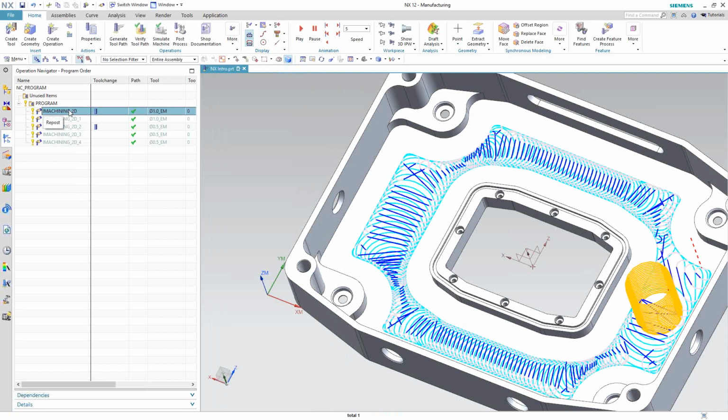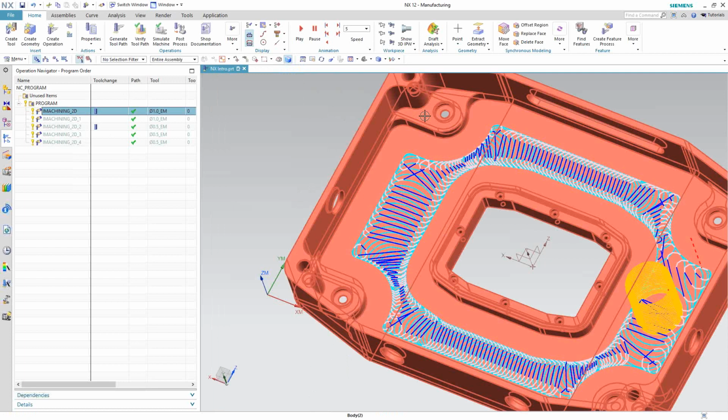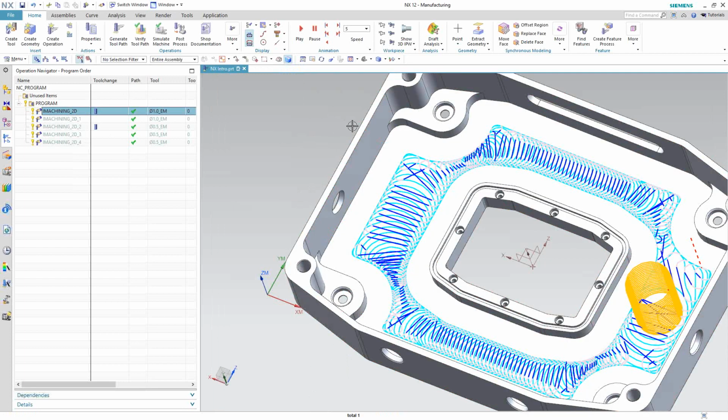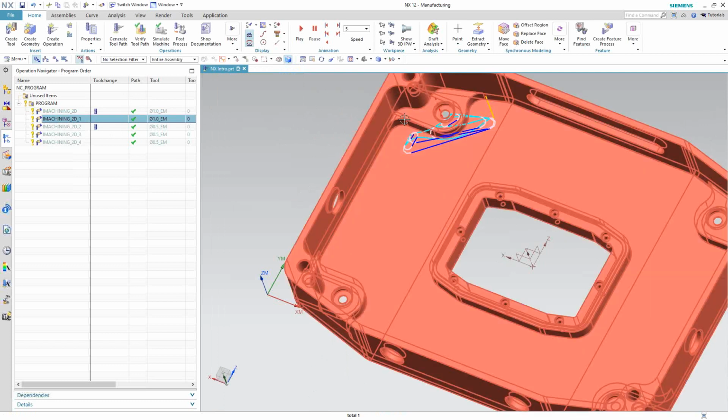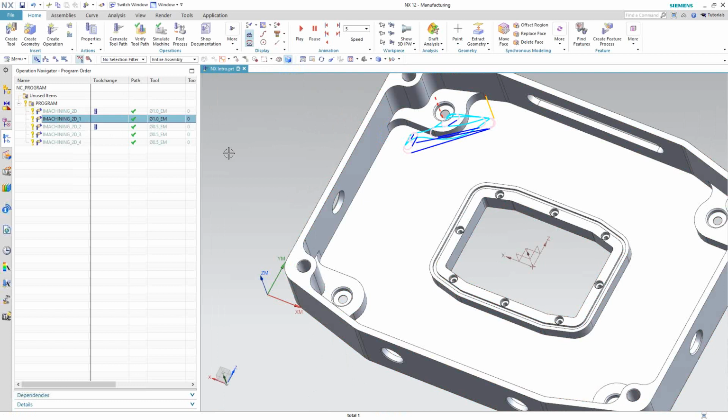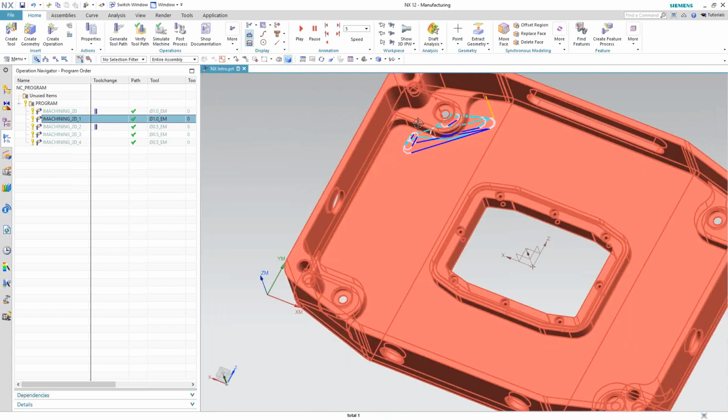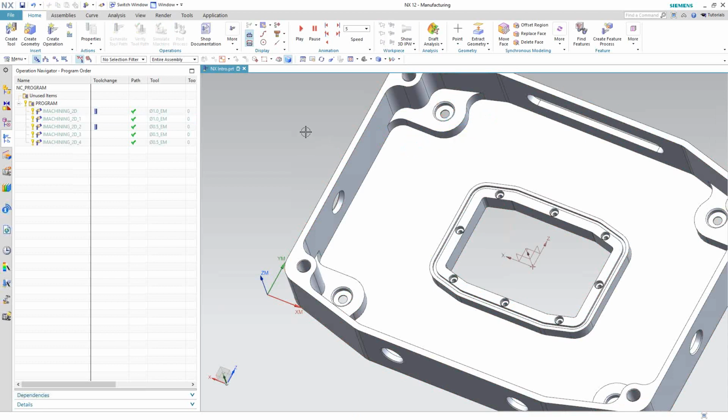So this was an example of iRough. I left 10 thou on the walls and the floor. I used a 1-inch end mill to machine down that bottom floor. If I wanted to machine these side pockets, well, one edge of that pocket is actually open, and we have the ability to do that. I set the geometry as all those edges along that pocket, but I told it that the back wall is a wall, not to cross those lines. The front edges are open, telling the software that the tool can actually cross those lines.